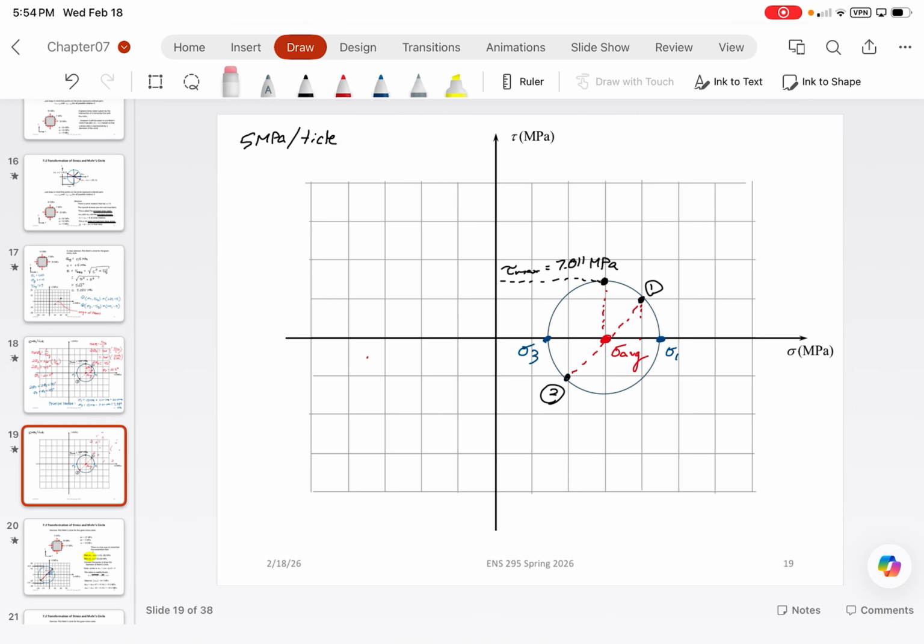All right. Now, let's say we didn't necessarily care about what the principal stresses are and we wanted the rotation at a particular angle, in other words, that 30-degree angle. Well, in that case, you would need to rotate this entire thing here. This angle here would just be 2 times our rotation of 30 degrees, which would give us 60 degrees.